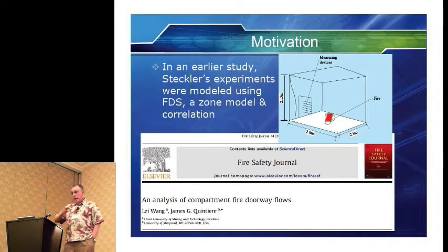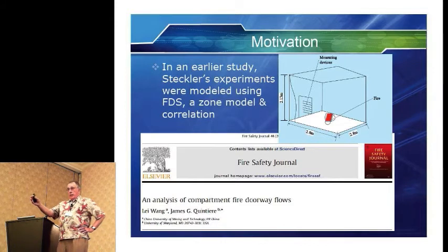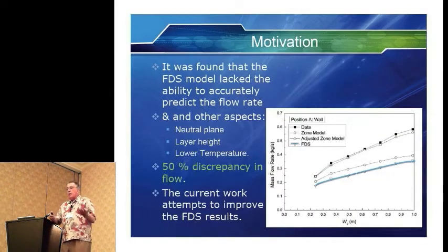These data have been used to validate many fire models over the period. Most of them are RANS, and so FDS has sort of taken over from RANS. In the validation guide, I see that there is a check against these data on the center line for velocity. So in our analysis, we went a little further.